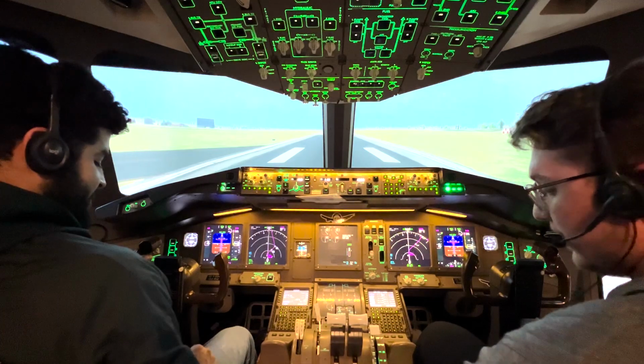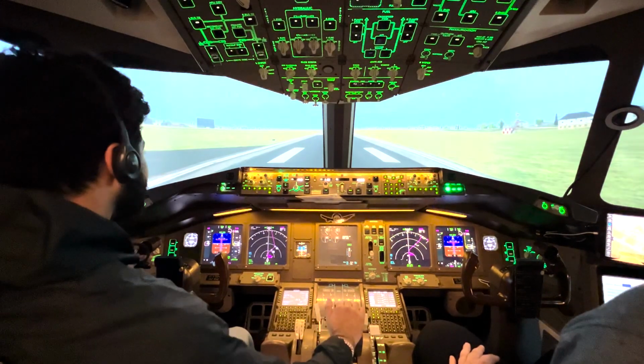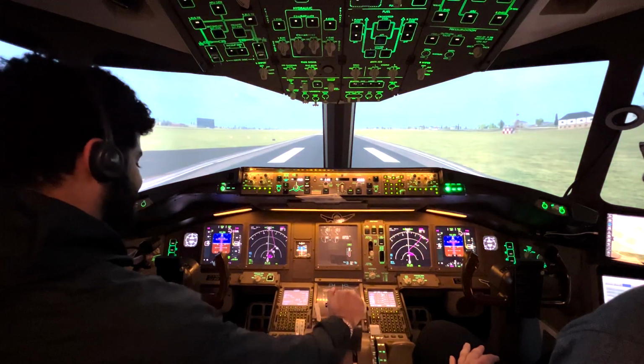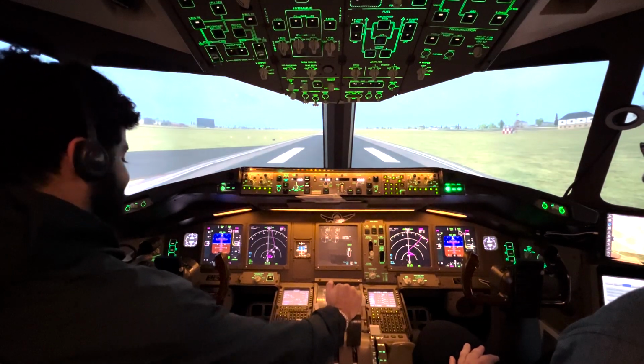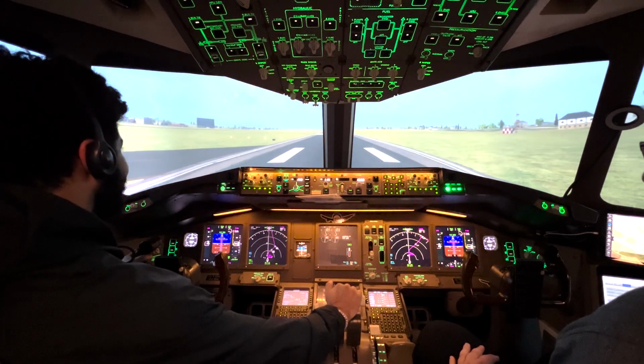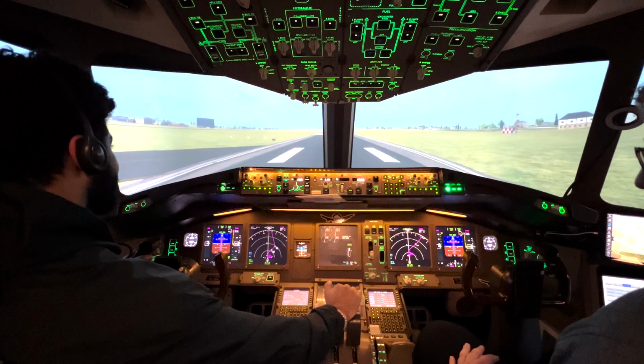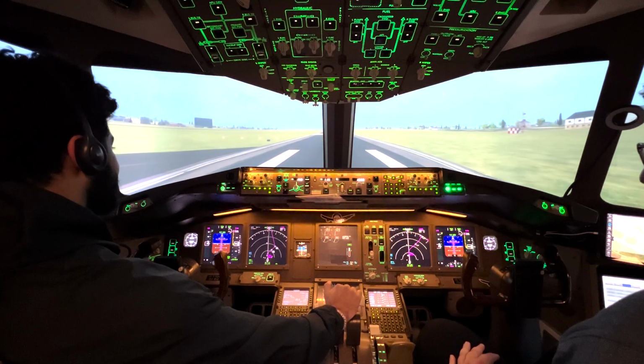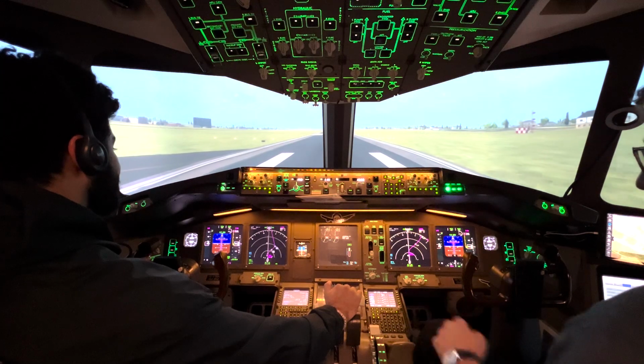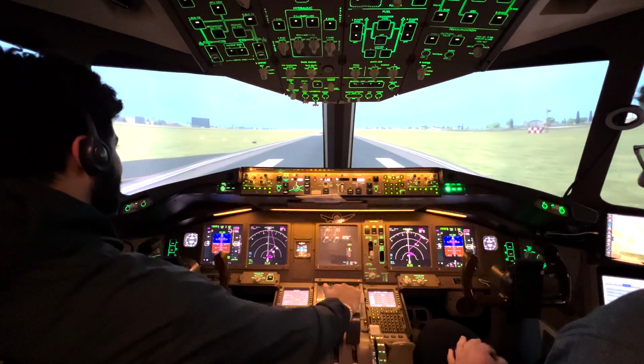So we're going to disable the parking brake. And as I said, 50% on that. That's good. So we're watching. It's stabilized at, we're going to wait a bit more, 47%. Both engines stabilized. Hit the button and let it take your hand with it.